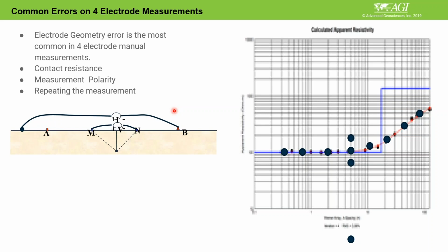I had clients doing very shallow studies, like 20 meters depth, 25 meters depth. So that means maybe a maximum of 50 meters, and then the maximum AB electrode spacing means 50 meters. They can see, but they cannot control exact locations. So operators sometimes say, okay, I see where they are, but you're not sure if it's here or here.